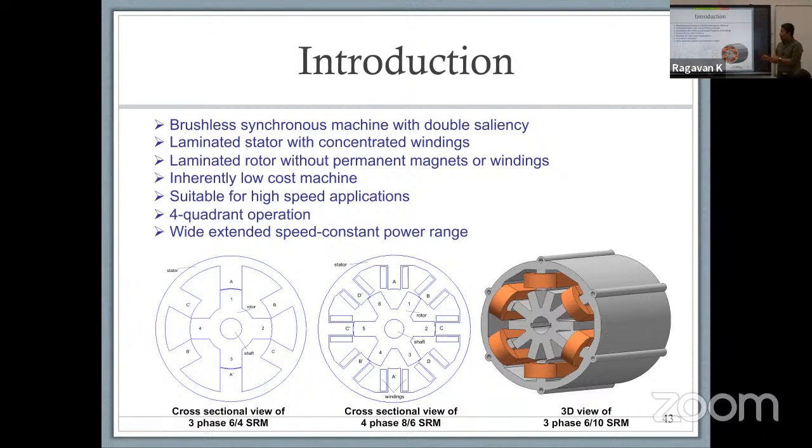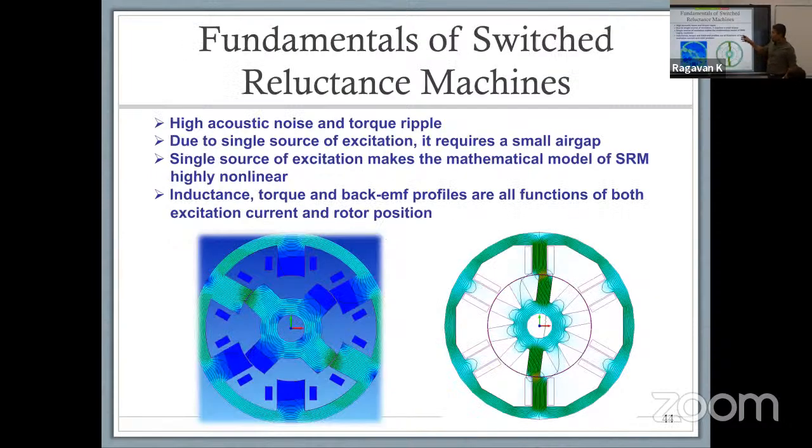So we looked at such electric machines primarily because they had benefits from a supply chain vantage point. We talked about that. We also looked at the fact that this kind of motor has the same field distribution, but it's basically going to give you a much better torque response.